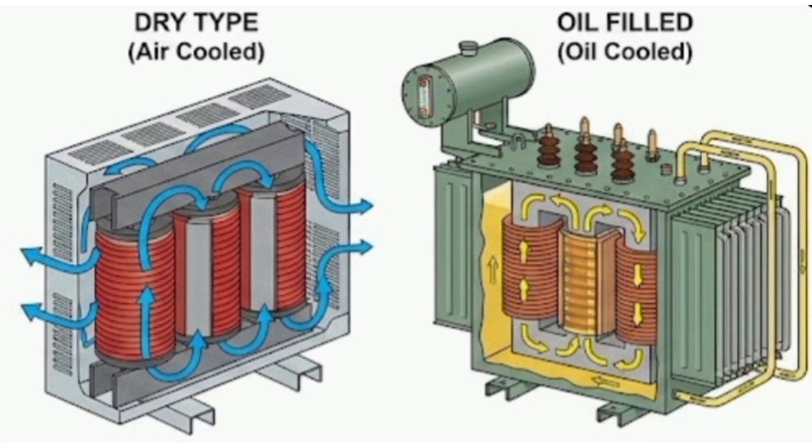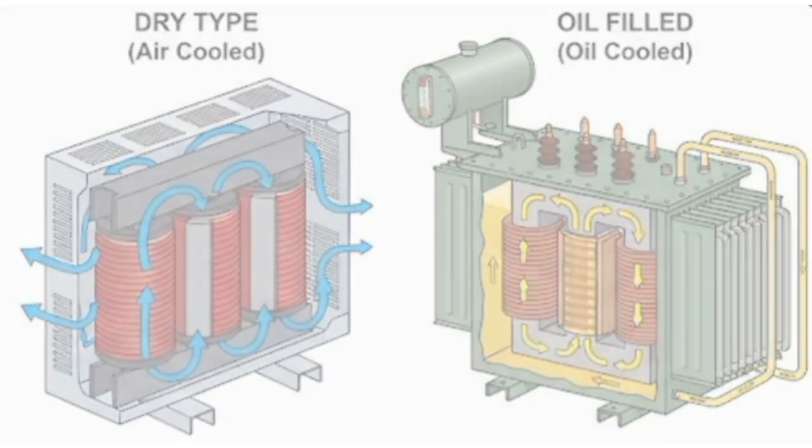Dry-type transformers offer superior fire safety, lower maintenance requirements, and greater environmental protection. Oil-filled transformers are typically preferred for outdoor utility and industrial applications, while dry-type transformers are favored for indoor installations where public safety is a priority.